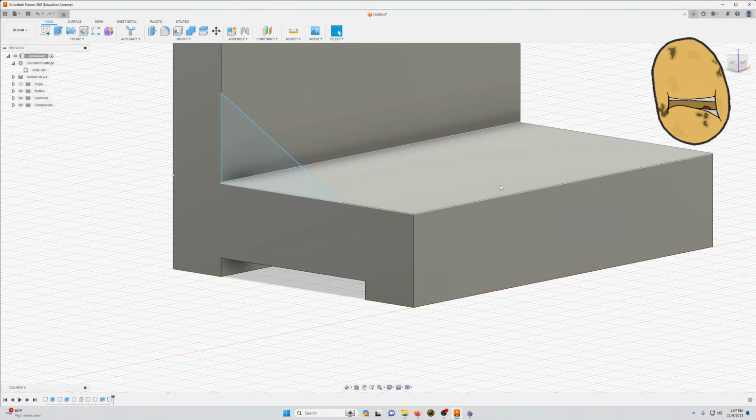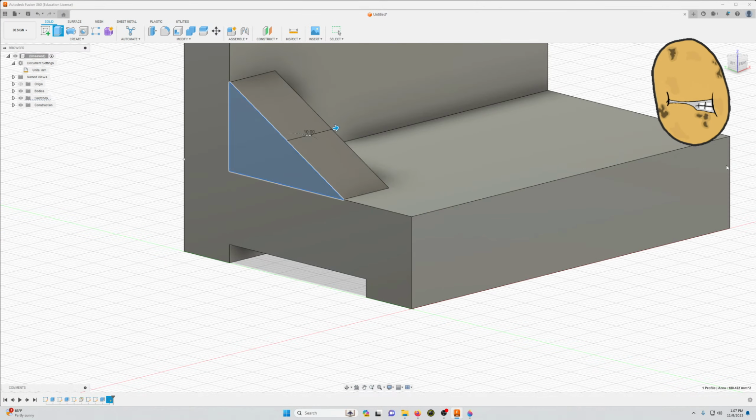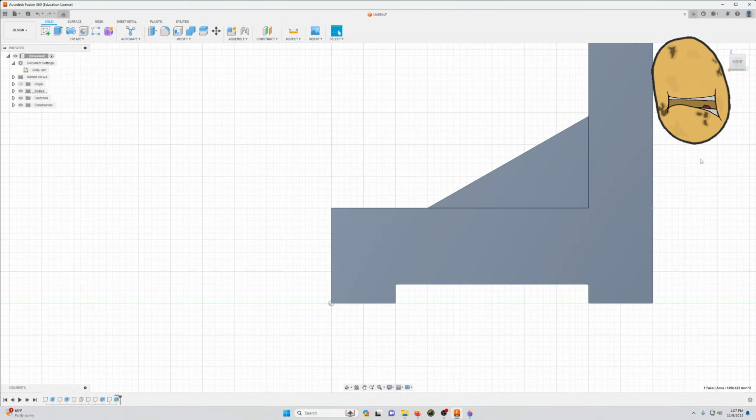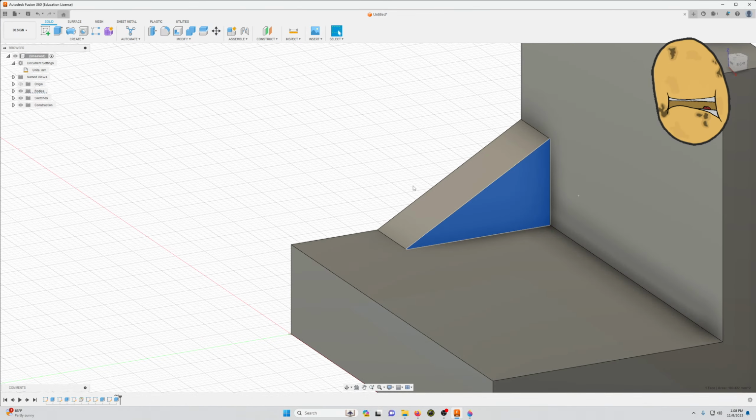And it is 10 thick. So we're going to go to extrude, and we're going to do it 10 millimeters thick. Now what I'm going to do with this little guy right here, I was going to copy that object and then just paste it on the other side, but I mean that works too. Unless I can just copy it face. Okay, do that. Move the face.